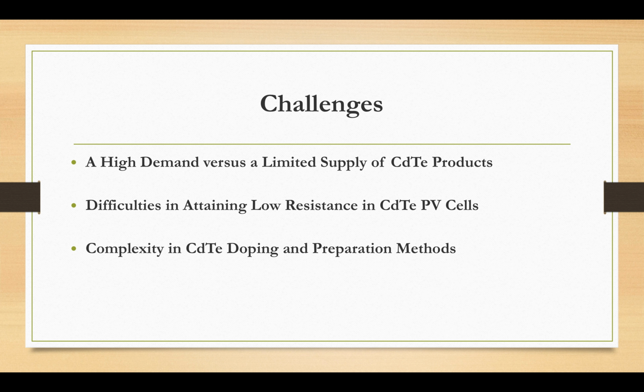The variability of results makes it difficult to discriminate the minor defects from the major ones. Cadmium telluride fabricated contact points are often weak, thus the contact technology is limited to a small number of possible choices for low resistivity P-type material.